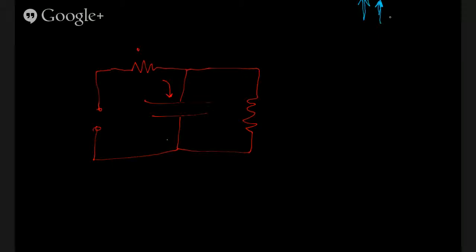And then generally, once the capacitor is saturated, you'll stop adding energy, usually with a transistor. So there'll be a transistor junction here, and once this capacitor is charged enough to turn on the transistor, it'll turn off adding energy, and it will discharge through this resistor.